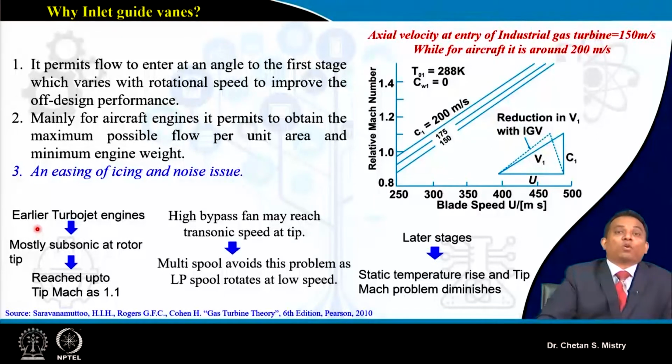That was the whole thought process. Later, during the 70s, people realized that in place of controlling this relative Mach number by rotating the wheel at low speed, we need to think of some other alternative, and that gave the idea of incorporating different transonic aerofoils.